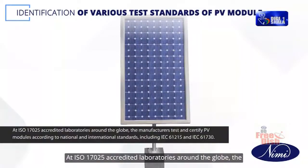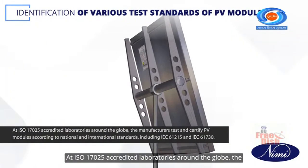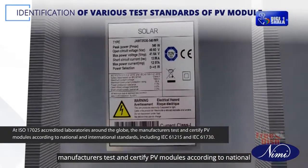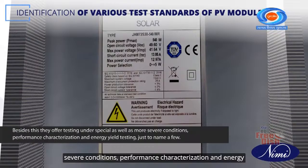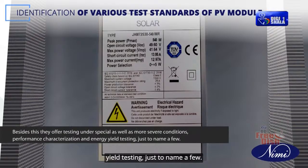At ISO 17025 accredited laboratories around the globe, the manufacturers test and certify PV modules according to national and international standards, including IEC 61215 and IEC 61730. Besides this, they offer testing under special as well as more severe conditions, performance characterization, and energy yield testing, just to name a few.